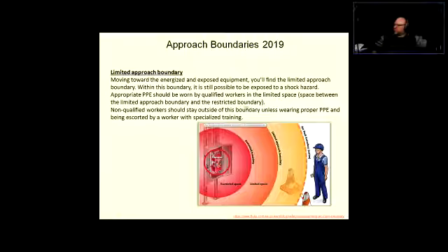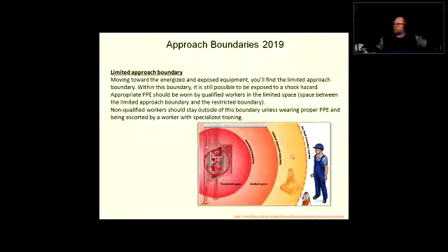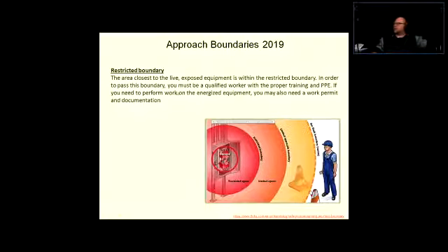Okay, I gotta read it a couple times. Non-qualified workers should stay outside of this boundary unless wearing proper PPE and being escorted by a worker with specialized training. So we can get a little bit closer being unqualified, but you should be trained or debriefed, and you should be accompanied by a qualified worker. I'm not sure who would want to, or why, but it's the rules. Maybe just a nature observer of electric equipment, right?